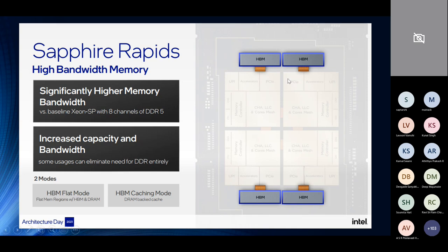Before, you would have either a discrete memory card or a discrete memory chip on the PCB, or completely embedded memories which are of very small capacity. Now what you have is these HBM tiles connected through an EMIB structure to your actual compute tile to be able to get the benefit of both worlds.